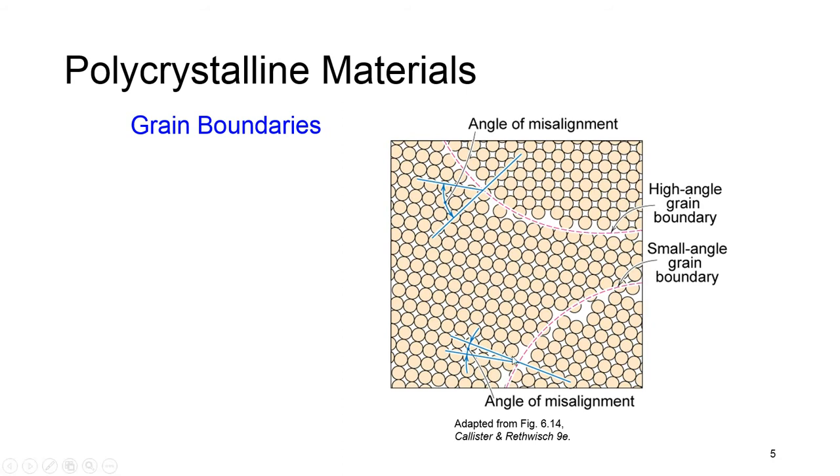less density in grain boundaries compared to the grains themselves. Because there is less density, of course there is high mobility, and some atoms can go inside this region, which is called diffusion, so high diffusivity and high chemical reactivity. If a material doesn't have different structures, that type of structure is called single crystal.